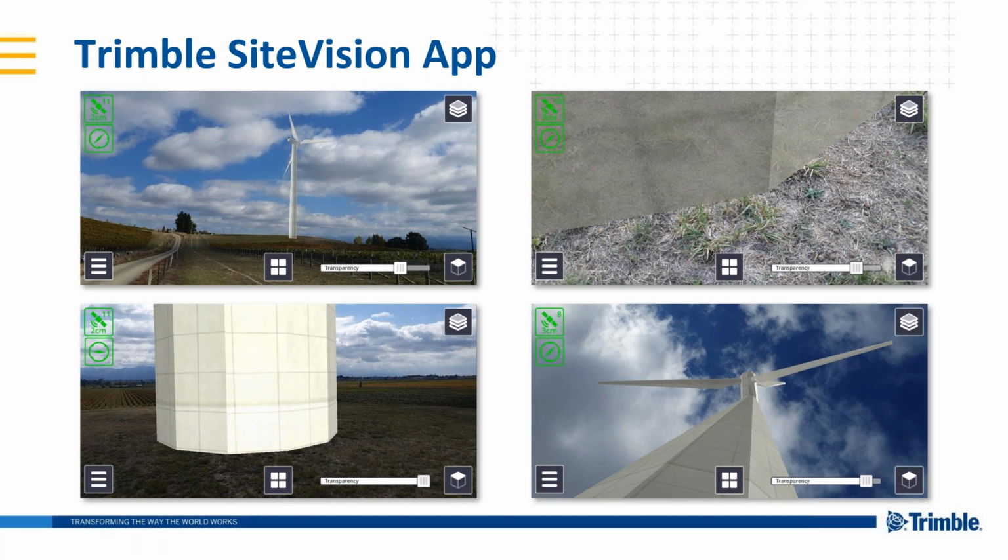Standing next to the survey rod, you look at the tip of the rod through the SiteVision system, and when the tip of the rod is on the corner of the foundation, or whatever component of the model it might be, the view through SiteVision is within 2-3 centimeters of what's being set out. So it's a very, very accurate system.